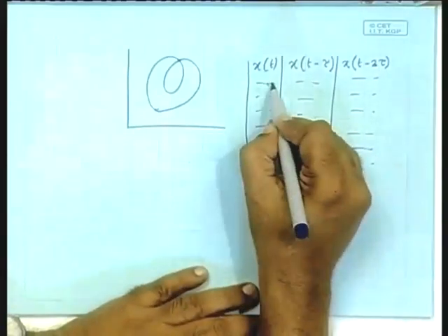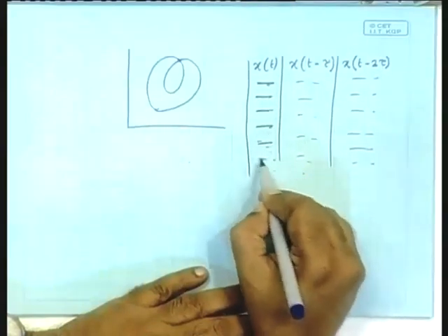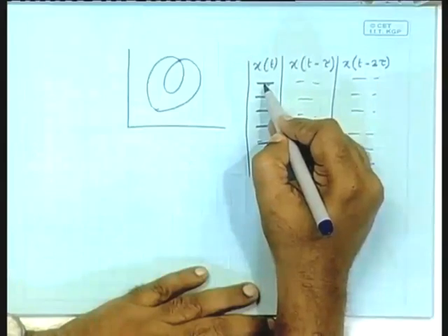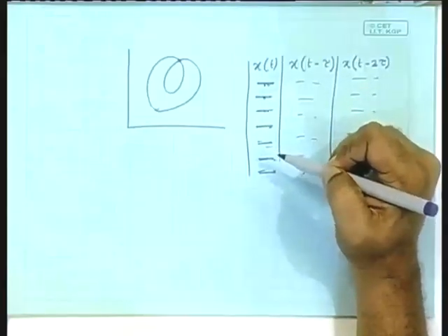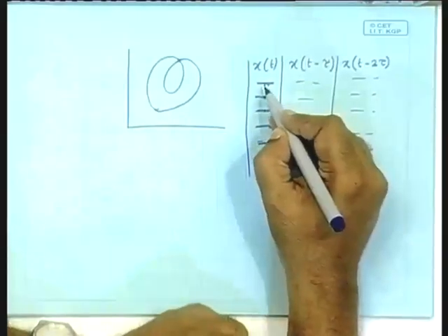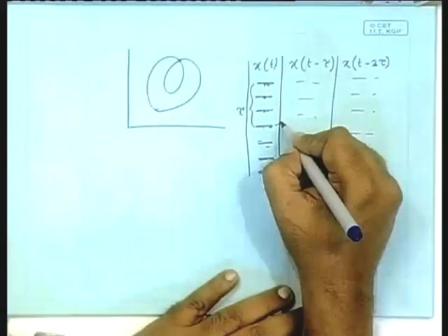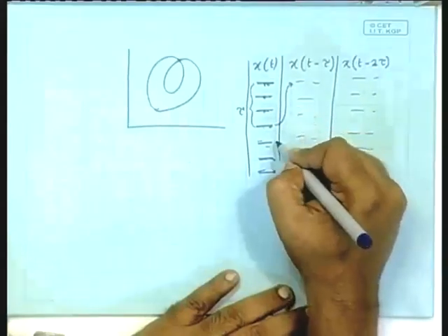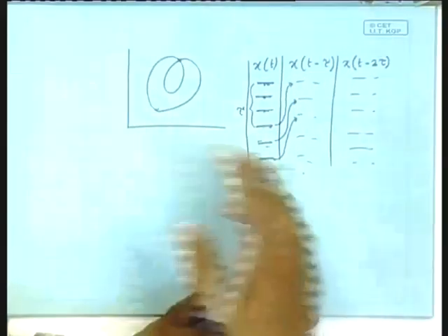which means what are you doing? Suppose you have got a data file in which xt are plotted, xt are given. So here will be one line here, another here, another here, and so on and so forth. This is x at time 0, and the time at the next observation instant here. For example, if this is generated by some kind of a data acquisition card, then this time difference relates to the speed of the data acquisition card. Okay. And suppose we have identified tau as 4 lengths of this. So this is tau, suppose. Then what we will do? We will put this point here, the next point there, the next point there, and so forth. Thereby generate a time series and plot.